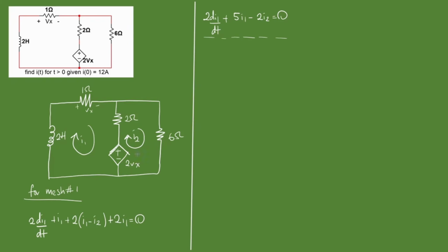So for solving for the second loop, let me write out mesh 2. Excuse my handwriting. Okay, that's a bit better. All right, so let's start with this 6I2, since we're meeting the resistor. 6I2 minus 2Vx. Our current flows this way, and we're going to meet the negative terminal of our dependent source. So minus 2Vx, that's minus 2I1. Vx is equal to I1.